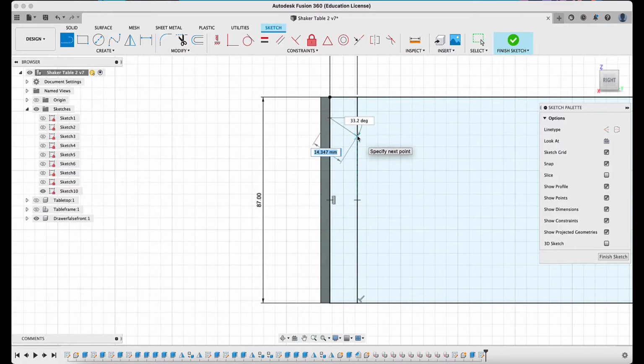And it's the angle that is important. Now, a little bit of theory here. Dovetail angles are usually done by a ratio. For hardwoods, the ratio is 1:8. For softwoods, the ratio is 1:6. In the module where we talk about dovetails, I go into that in a little more detail. But in this case, we're going to use a 1:8 ratio. The angle of a 1:8 ratio is around 7 degrees. It's 7.1, but we'll just say 7 degrees. So what I'm going to do is just press Tab, 7, then Enter.